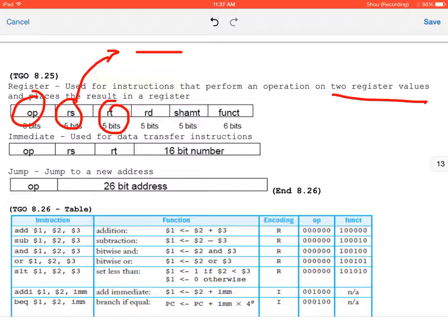Then it goes to the arithmetic logic unit. Some operation is performed. In this case, we have selected addition. And then it's stored back into the 32-bit value indicated by RD. So that's our write line. Shift amount: if we're doing a shift left or shift right, we can potentially shift up to 32 bits, or in your 8-bit data path in this course, 0 to 8 bits. More often than not, shift amount will be 0.